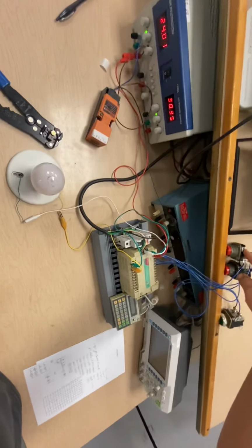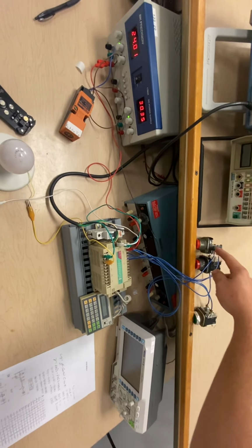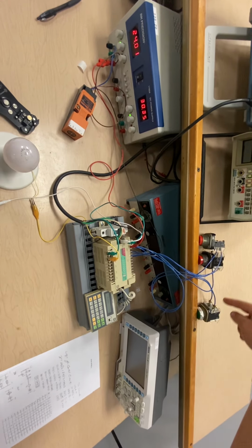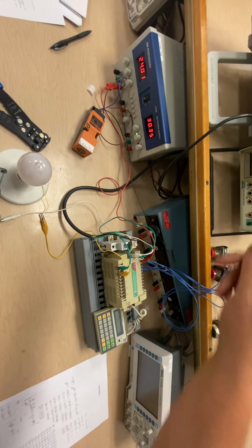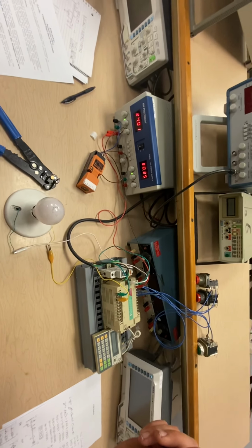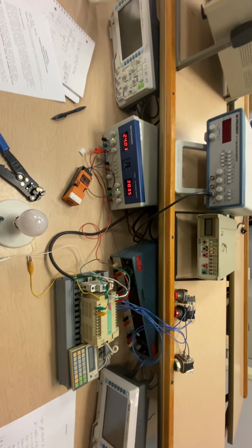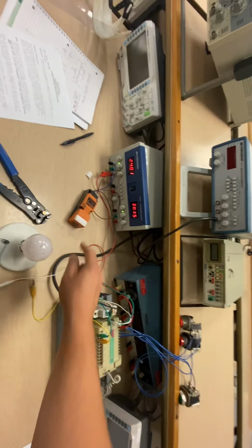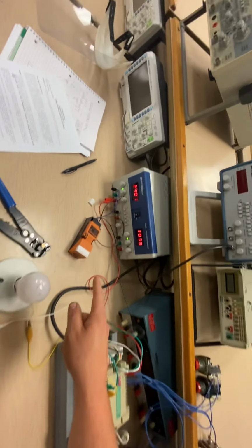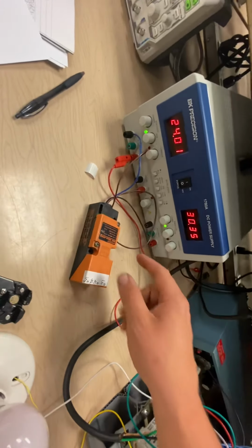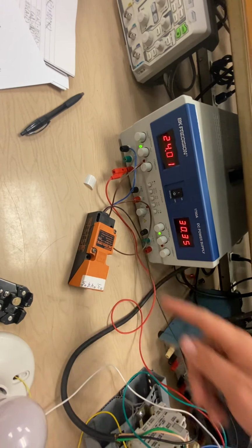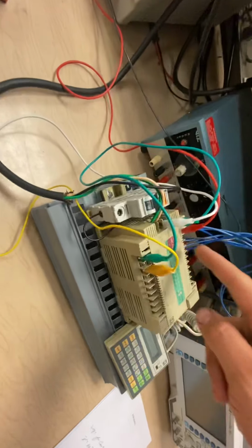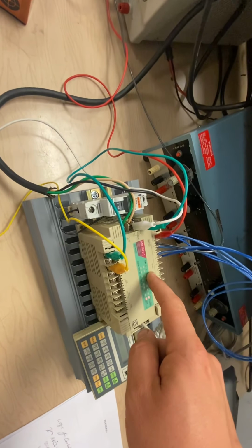So our circuit goes as follows. This is A switch, B switch, C switch, and our proximity switch. Now our proximity switch is sourcing, so we have to run power and ground separately, and then we run the output to our microcontroller, which is a sinking function.